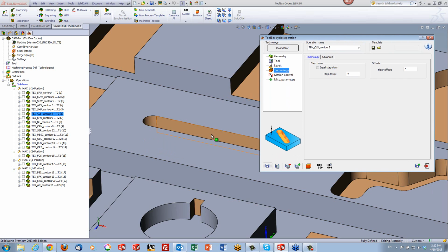I couldn't even count them. So originally, with the way he used to do it, creating a line in the middle, it was a very tiresome operation. But all he had to do now is just create the geometry by clicking on the face with multi-chains, and use the actual geometry that was on the part itself without creating any lines in the middle. Made life a lot easier for that person.